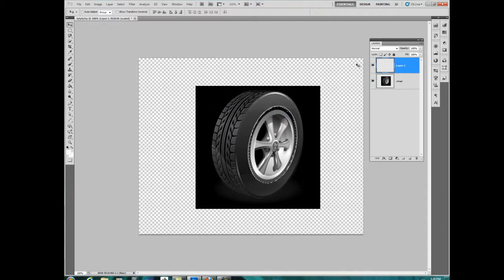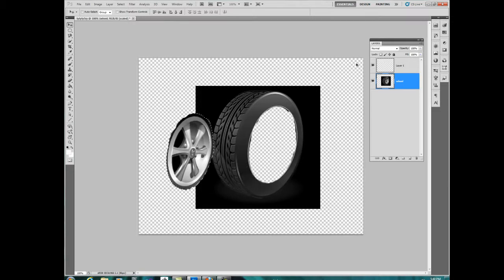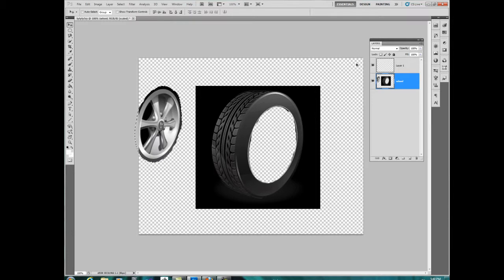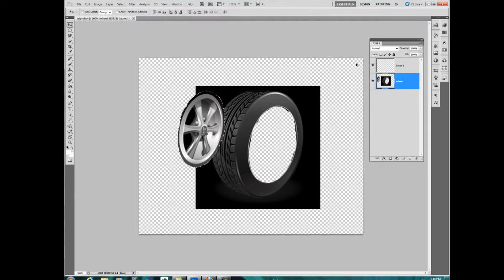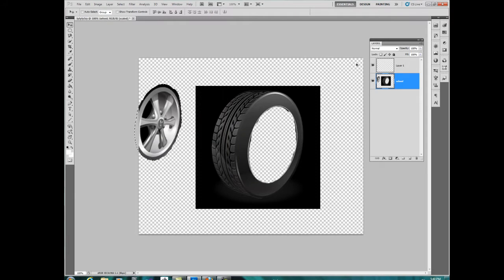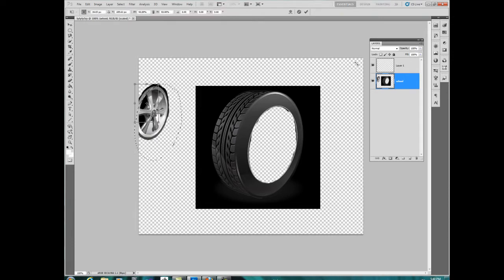I'm getting that error because there's really nothing selected because I'm on the wrong layer, as you can see. I have to always remember to have that layer selected. So what I'm going to do is I'm going to have that layer selected now. Now if I hit V, now I can go ahead and move it out. Okay? So I go ahead and move that out wherever I want. And we go back to the original tool that we use. We go back to the translation tool, and that's Control T, and now I can translate it whichever way I want.